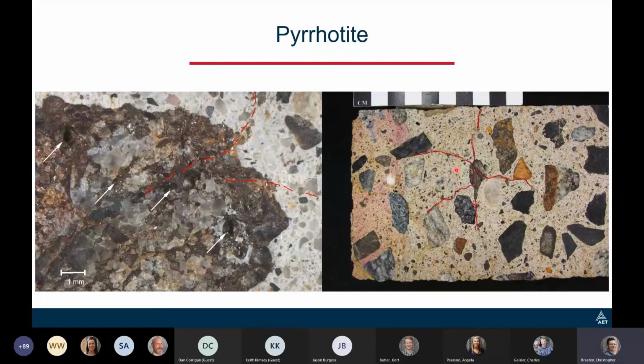The other thing that's going on right now is, and I don't know if this happened yet, but last I saw in 2021, there was a petition for the adoption of a bill in Massachusetts about how to deal with pyrrhotite and how quarries and aggregate producers have to look for and test for pyrrhotite. So it's a big deal out there. A lot of insurance agencies are getting on board. We got quite a few concrete cores from insurance agencies trying to see if it really was pyrrhotite or something else. Because I think the state might have put money towards helping people pay for repairs if they could prove that it was pyrrhotite. But very interesting nonetheless. Sucks to be those homeowners. I get it, but as a geologist and a concrete petrographer, it's interesting stuff.